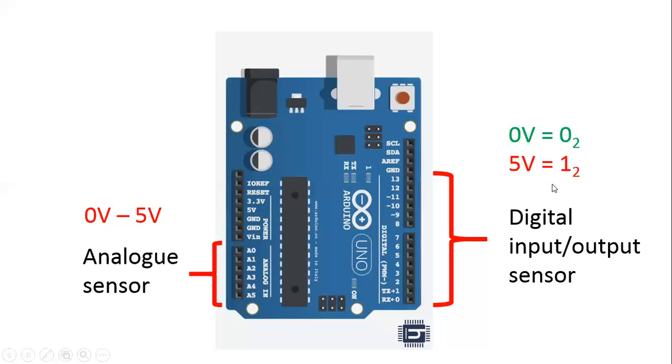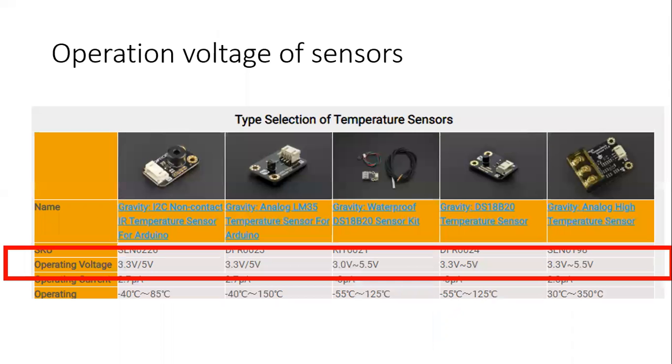You use digitalWrite to assign a 1, meaning the output will become 5 volt. Use digitalWrite to write a 0 or low, and the output signal will become 0. So digital is normally used to control other actuators, or a transistor, relay, and any other driver.